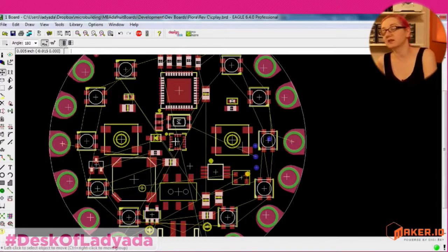This is a single-sided design. Single-sided boards are going to be a lot cheaper than double-sided, because with double-sided you have to go through the entire process twice. So your assembly costs are basically double, because your bill of materials is the same, but the assembly costs are double, and assembly costs are a couple bucks, so doubling it can make a big difference. If you can make your board single-sided and have everything be surface mount, that will reduce your cost quite a bit, or keep your costs under control. So that's why you see a lot of maker projects that are surface mount only and single-sided.